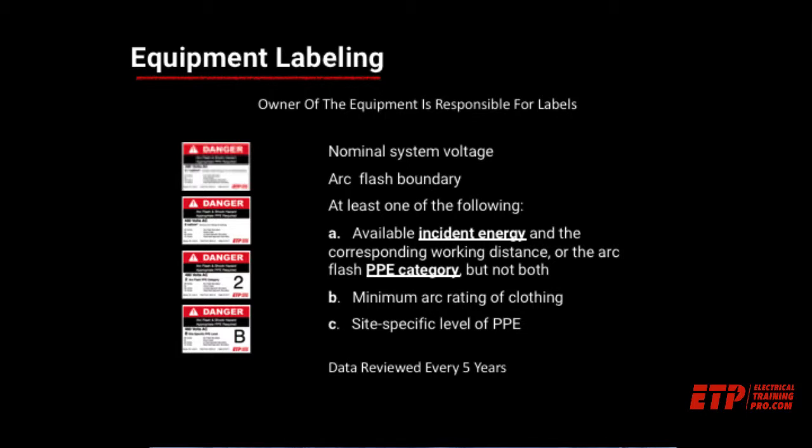I used to own a company that did hundreds of arc flash studies across the nation, and it was typical several years ago that we would put incident energy and the PPE category on the same label. Well, starting in 2015, it stopped being allowed. You can't have incident energy and a PPE category on the same label.